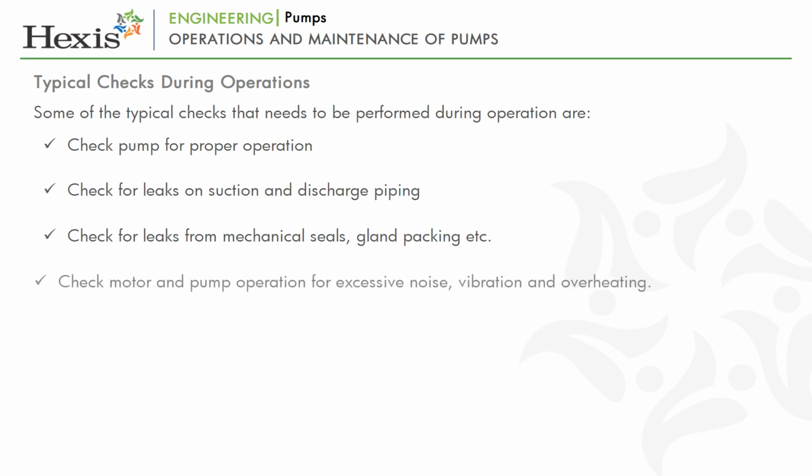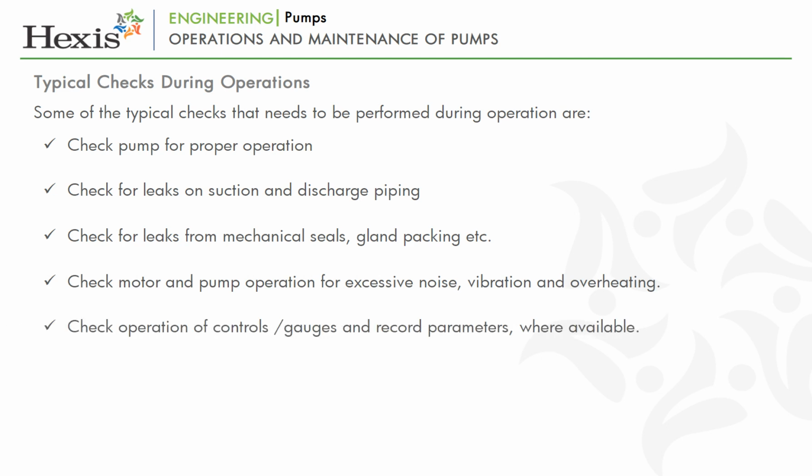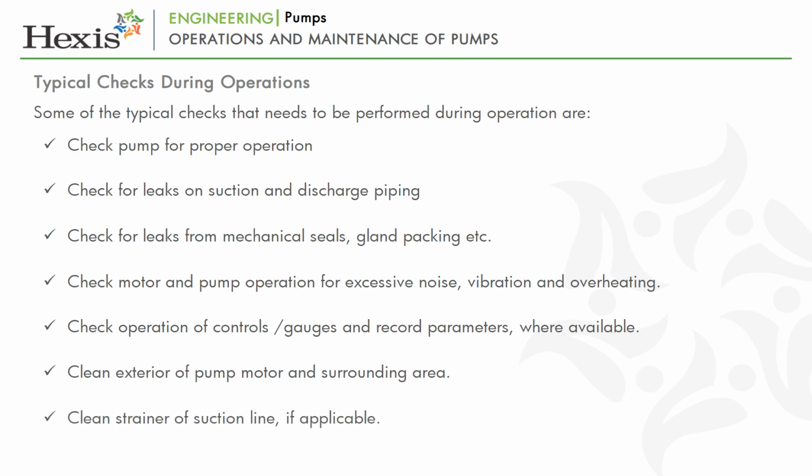Check motor and pump operation for excessive noise, vibration and overheating. Check operation of controls or gauges and record parameters where available. Clean exterior of pump motor and surrounding area. Clean strainer of suction line if applicable.